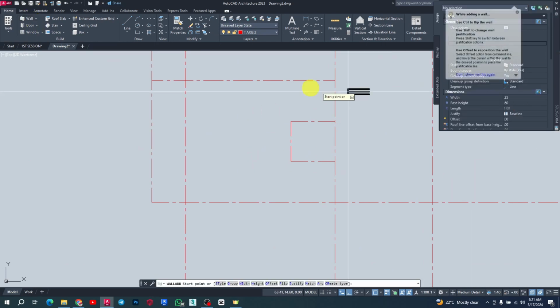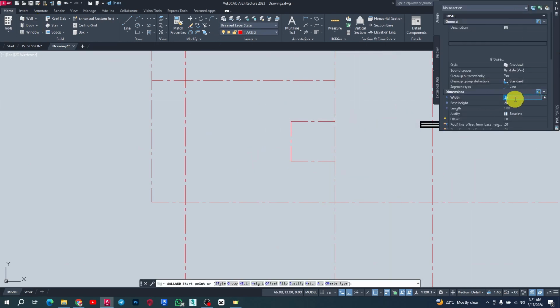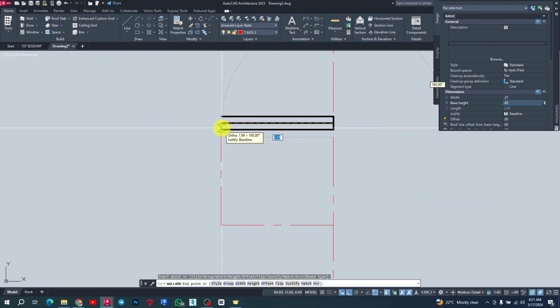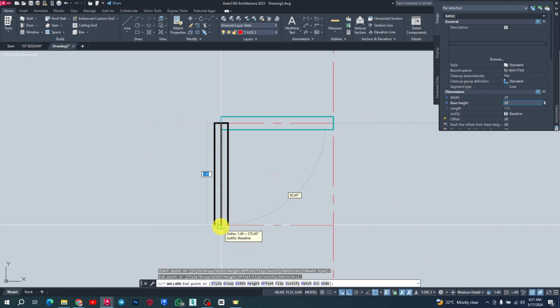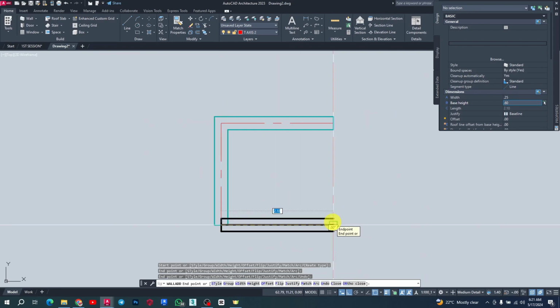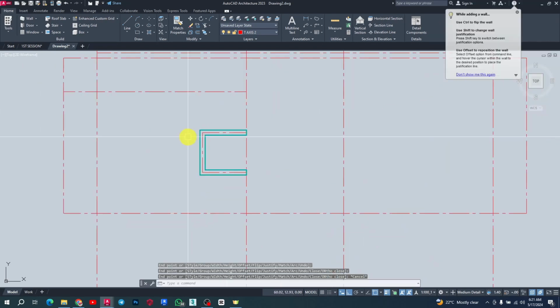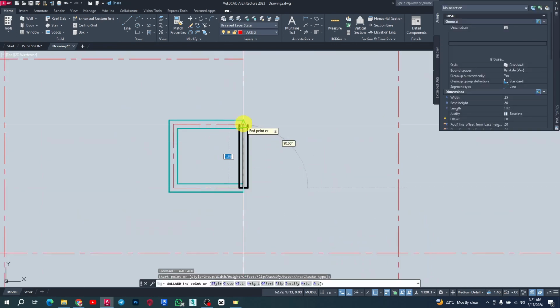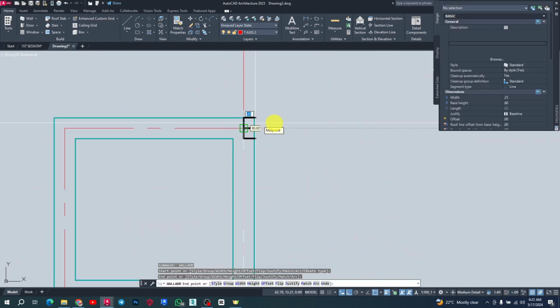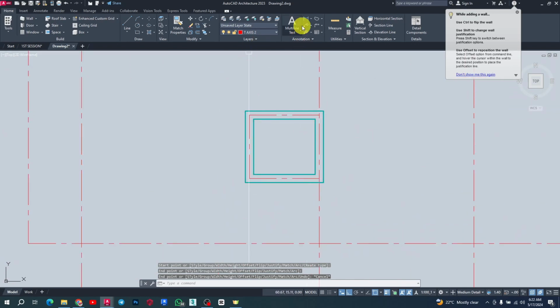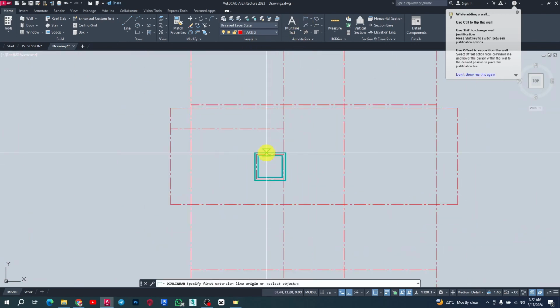I want to use a wall to just highlight that right away. So on my wall, you see the thickness is 0.25, so you can always change your thickness. You give it a height. Okay, so in this case it's not actually a 3D presentation that we are doing, so you can leave the height to be 0.6, whatever height that you want to go with. The main problem here is the thickness that we are going with. Okay, so I'm just going to click, and since I'm using the center line, remember I said I'm using the baseline, justify its baseline. So center line for me there is what I want for the thickness of my shaft, the wall of my lifter. Okay, so that is it.